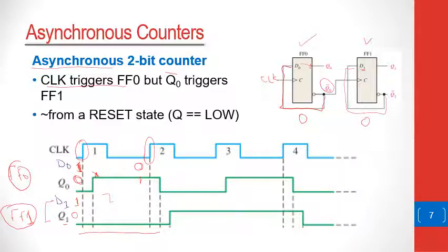So when the next clock moves, on the positive edge of the clock, that 0 would now move from D0 all the way into Q0, which means flip-flop number 0 will flip its state.